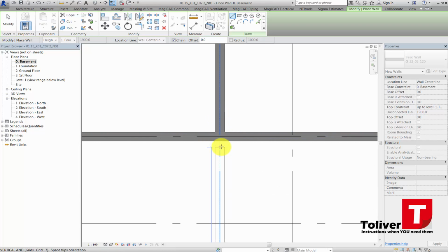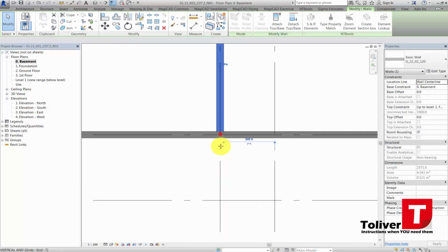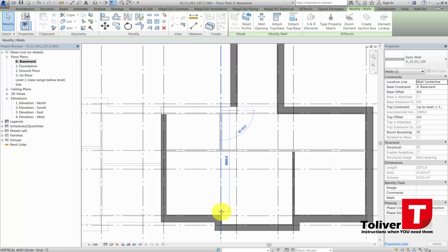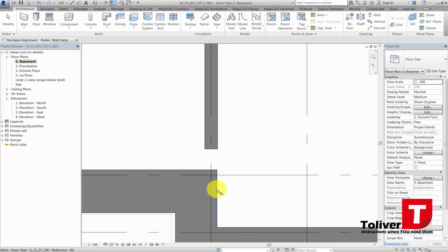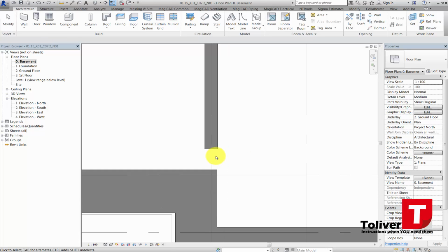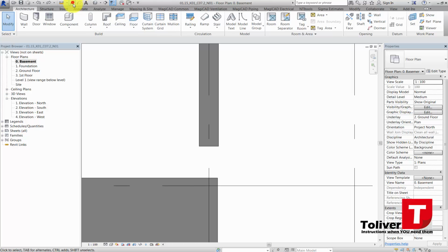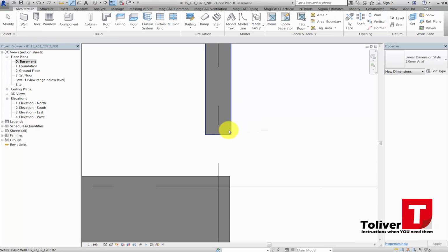and then this wall needs to be moved. So we're going to take this wall, drag it down like this, and say align AL. That one's supposed to be aligned with that one, and you know what, we're just going to undo that because I need to figure out what is actually the distance that is, like that, 6 millimeters.